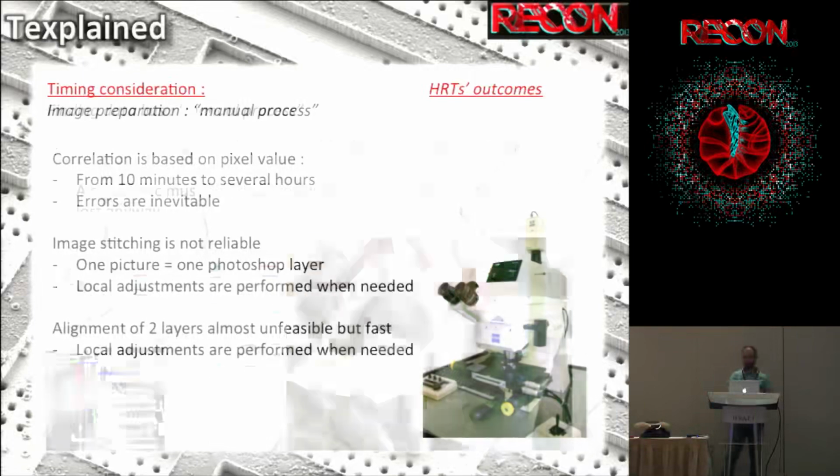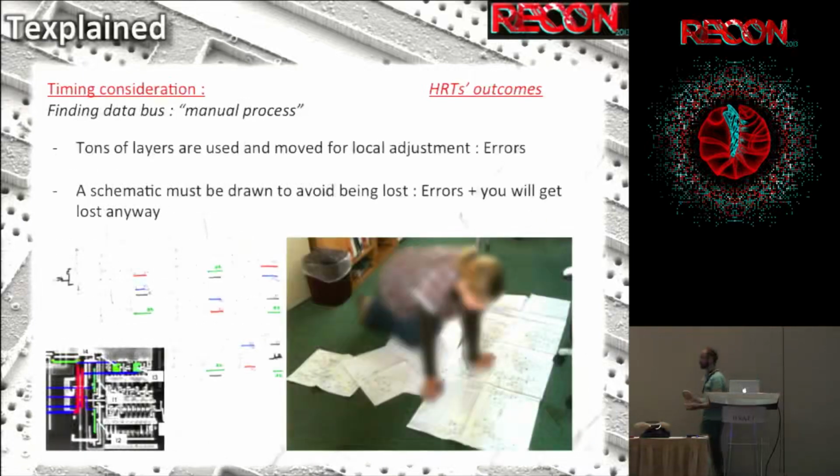And now what you do is you trace your lines by hand: I have a line here, and a line here, and here a line. You have to go from layer to layer, find the gates, identify the gates, write down what it is. And it's huge. We are speaking about huge. In that case, it's only 1,000 gates, but still, and you will start to draw a schematic somewhere, not to get lost. And if you do it with paper, you will have paper everywhere, with schematics.